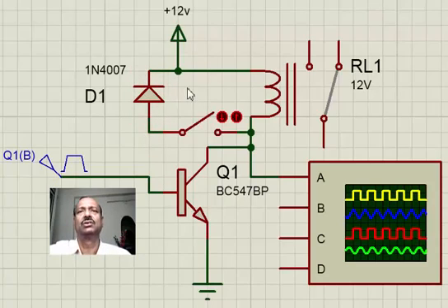As simple as that. So when the relay is switched on and the power supply is positive here, the relay switches on through this. The current flows from here to the coil and then to the transistor, to the ground, to the negative. But when we switch it off, supposing the transistor switches off and the relay in the process is switched off, what happens? The current will try to flow here, but since there is no path because the transistor is open, it will try to force a voltage across the transistor, which may eventually result in failure of the transistor. To avoid that, we provide a path by this path.